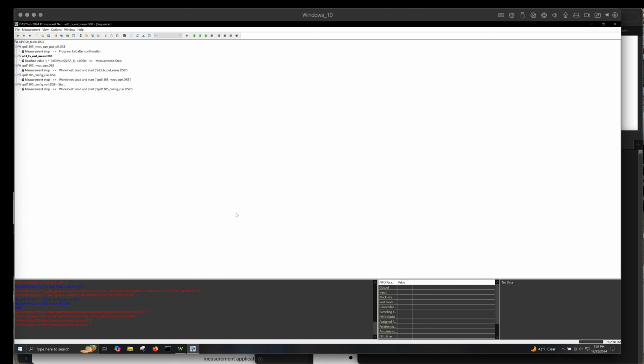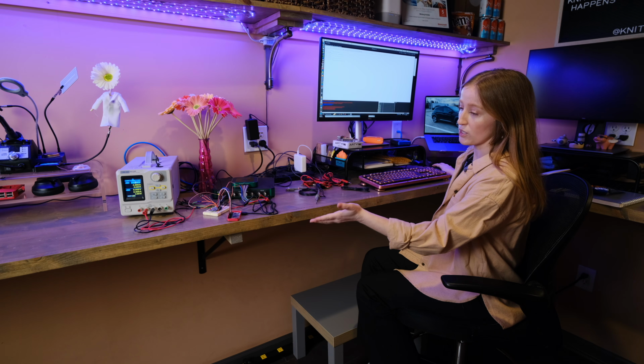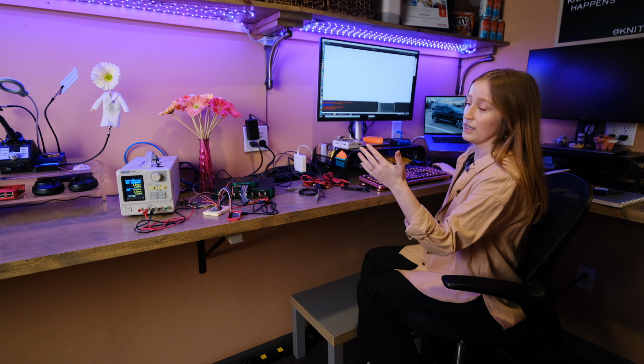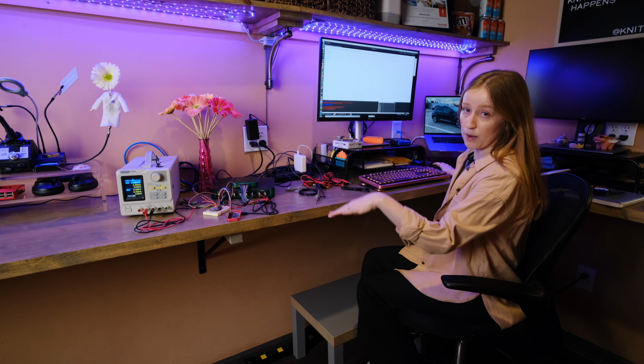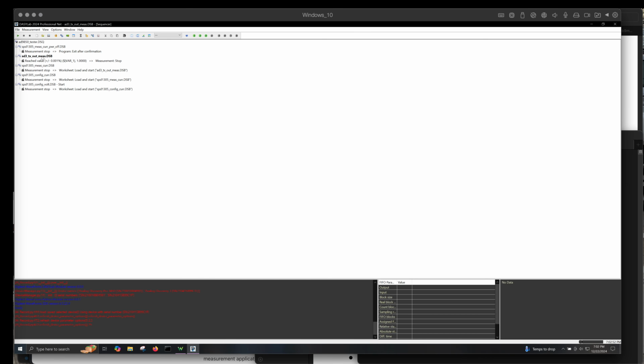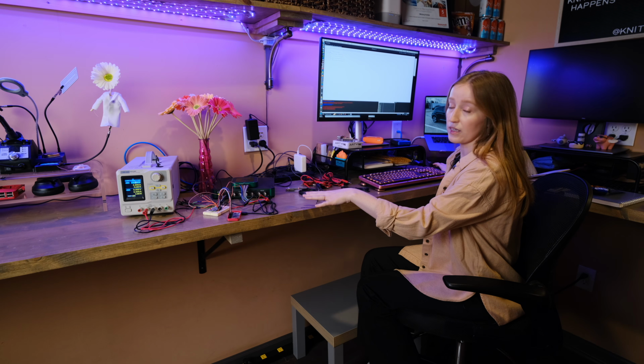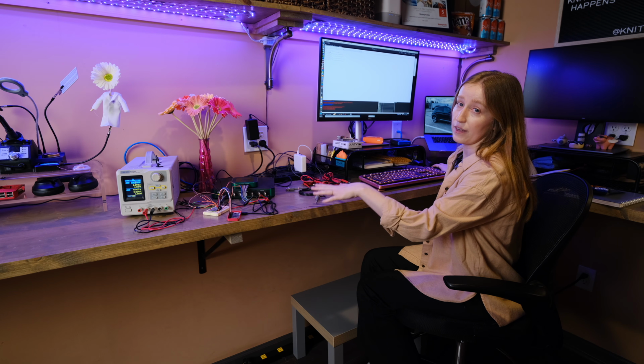So in the sequencer in DAISY Lab, I've called out each of my individual programs. I have my starting worksheet, which is the one that configures the voltage on the power supply, followed by the worksheet that configures and validates the current, followed by the current measurement worksheet that turns on the power supply and then measures the current until the Raspberry Pi Zero reaches its operating current, at which point it launches my final main tester worksheet, which is monitoring the analog output from the AD9850.